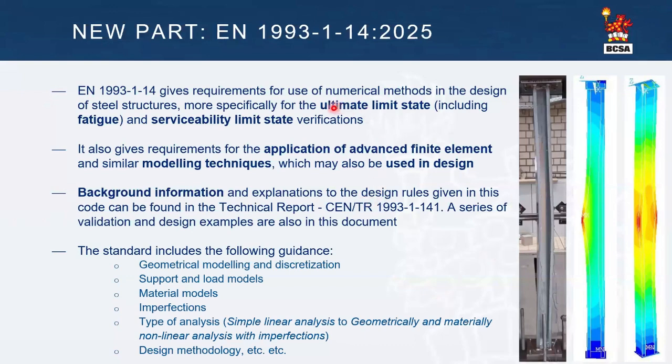Paraphrasing the scope of the standard, Eurocode 3 Part 1-14 gives requirements for use of numerical methods in the design of steel structures, including ultimate limit states, fatigue, and serviceability limit states. It also gives requirements for the application of advanced finite elements and similar modeling techniques, which can also be used in design.